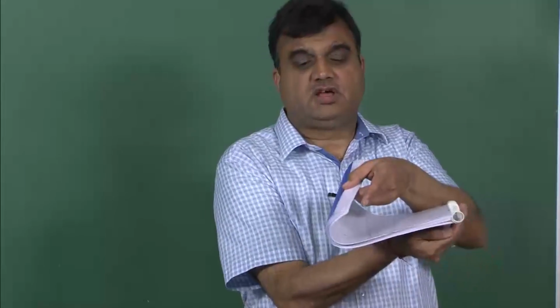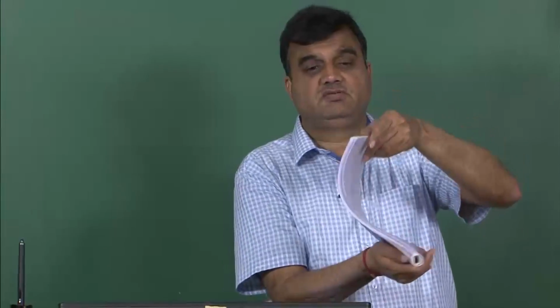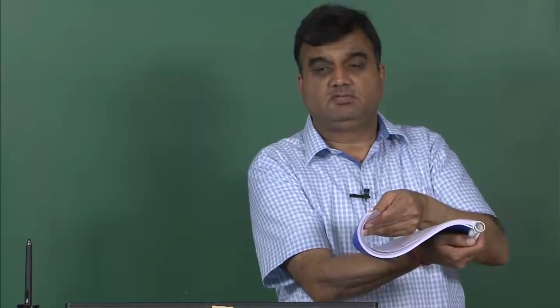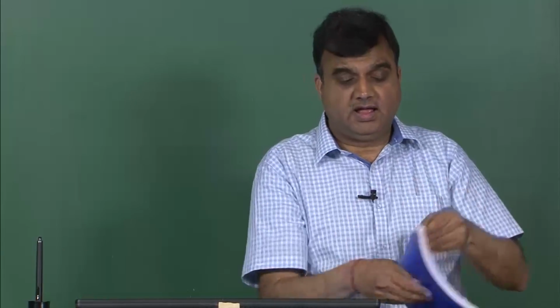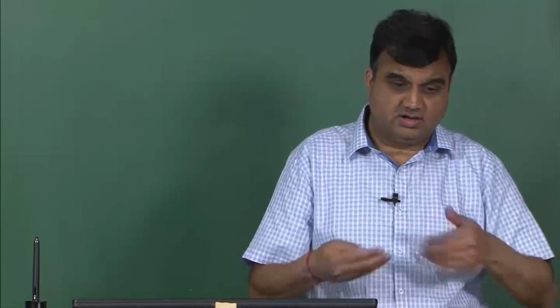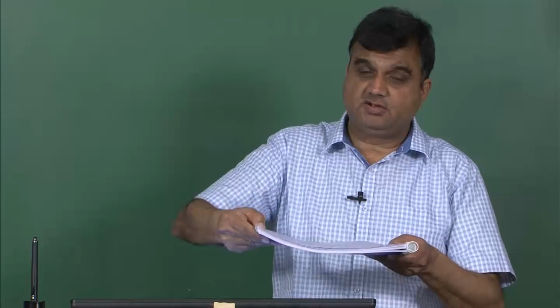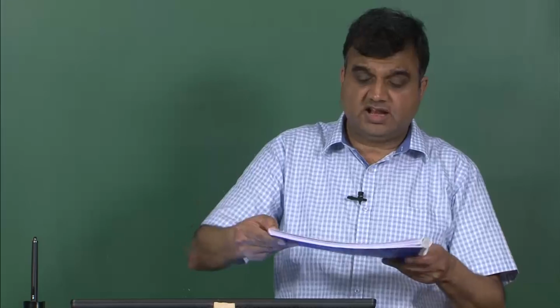So, this is how the edge will look. When it is not bent, the edge is straight. When it is bent, the edge becomes longer, and also each layer slides on top of or below adjacent layers. But when the bond is perfectly rigid, which means when I bend it, there is no sliding going to happen, and when there is no sliding going to happen, then,